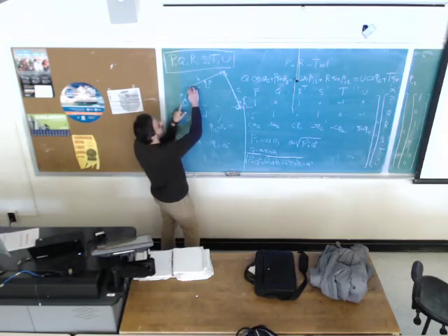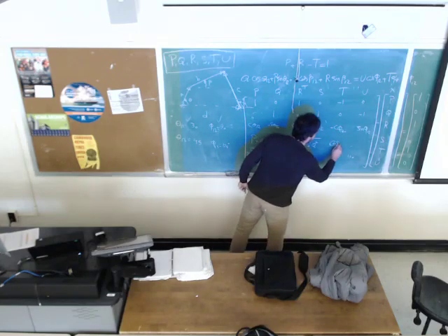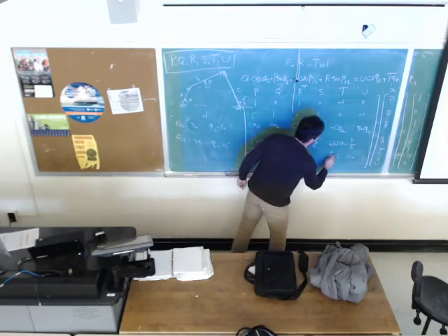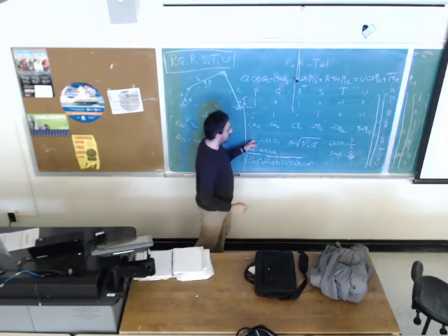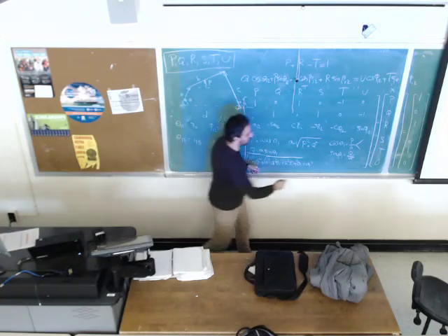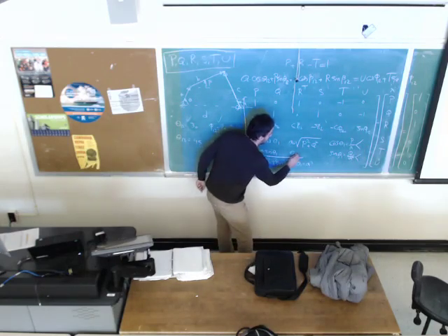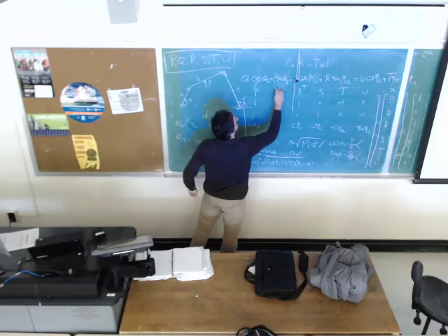You find A, you find this length. What would be the location of the second link at the first precision point? We are looking for theta 1. Cosine of theta 1 will be P divided by A. Sine of theta 1 is Q divided by A. You have P, you have A, find two angles here. You have Q, you have A, find two angles there. Find the matching pair. So theta 1 can be calculated by looking at P and Q.